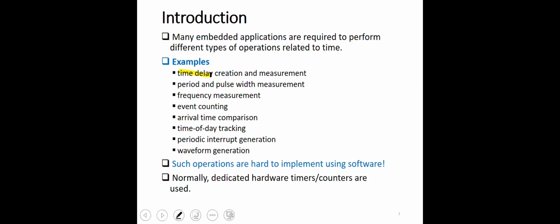That's why, if your time delay is used in some sensitive application where you cannot tolerate a change in the delay value, and you need to enable the interrupts, then the software-based approach for generating time delays might not be useful, because the time delay might increase in case there is an interrupt.